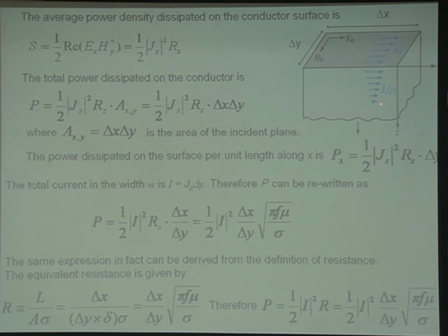Therefore, this current is almost entirely on the surface, so we can calculate a surface current. But this surface current is the current per unit length, so we do not care about the details of the distribution underneath, because it has all been lumped in here. But for this calculation, you cannot ignore the details in this direction, because you are calculating R from circuit theory. You have to have a cross-sectional area.